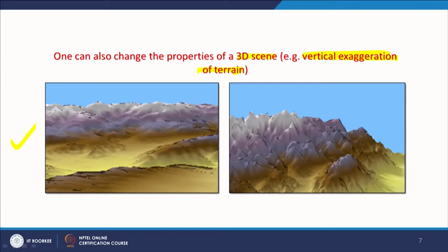One has to be very careful while increasing this vertical exaggeration, because it is not giving the real picture, it is exaggerating things, as the name also says. In Google Earth also you can introduce vertical exaggeration and see. This is very useful if you are going over flat terrain, like a desert area or the Indo-Gangetic plain, and you are still looking for undulations or ruggedness in the topography, the ridges, valleys or depressions.